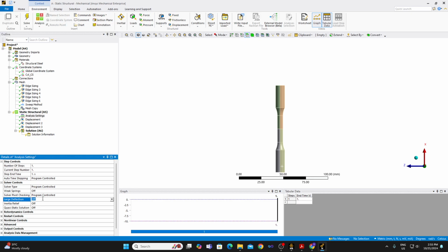Next thing is we are going to do an elastoplastic analysis, which means the strain here is going to be more than 1 in 1000. Once again we are considering metallic materials, and in metallic materials the elastic limit in terms of strain is about 1 in 1000. By the time a 1 meter length metallic rod has had an elongation of 1 millimeter, it has already yielded and already started having plastic deformations.